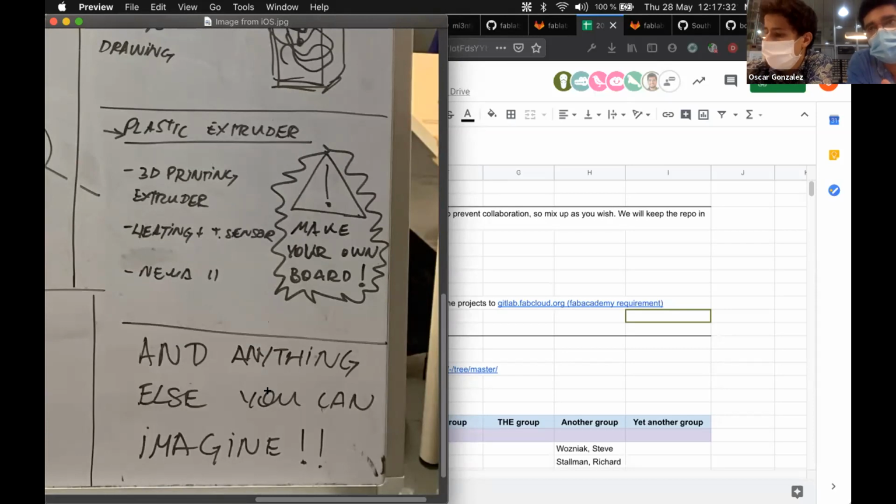That's easy because we have the power MOSFET. You will need to make a small PCB for the temperature sensor with a voltage divider to get proper readings. And you will need to make an external driver board to be able to run the motor of the extruder, if you want to have full control as in a normal 3D printer.